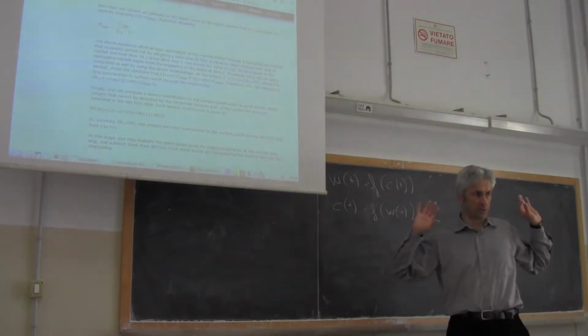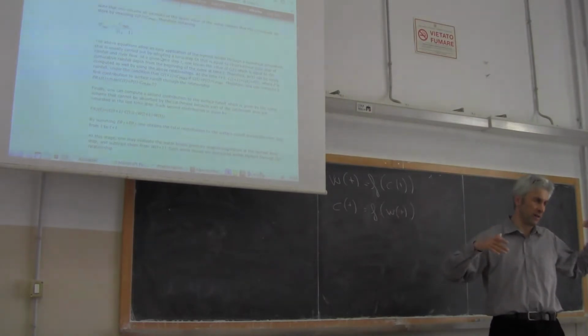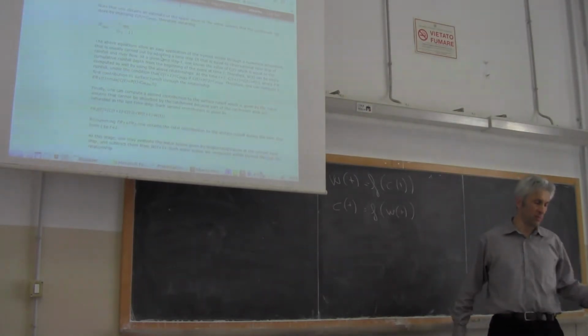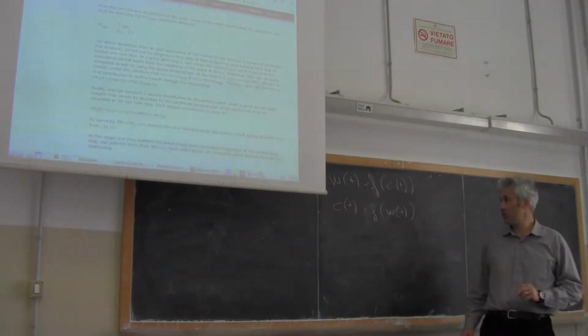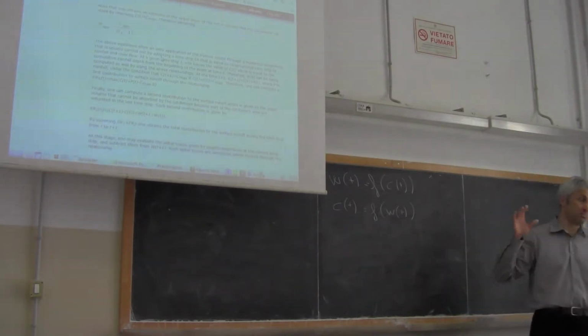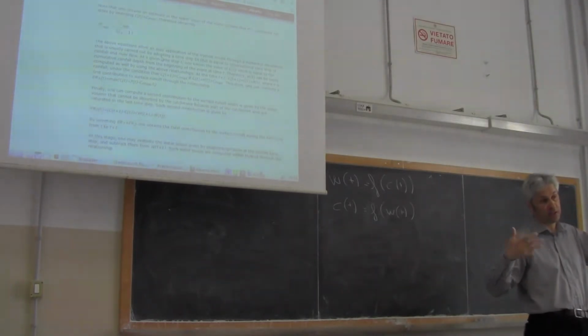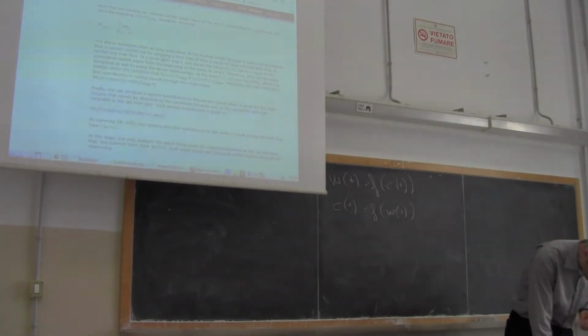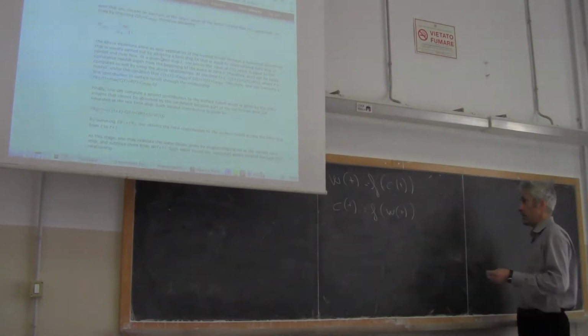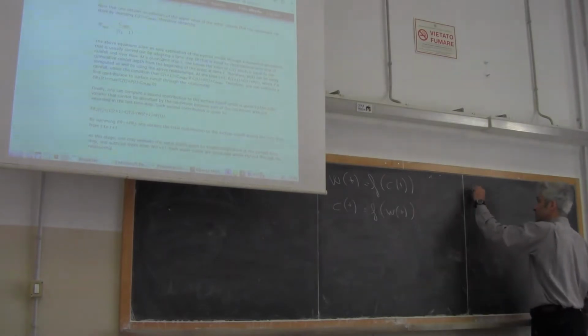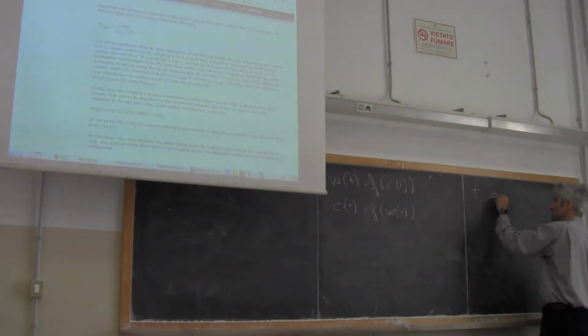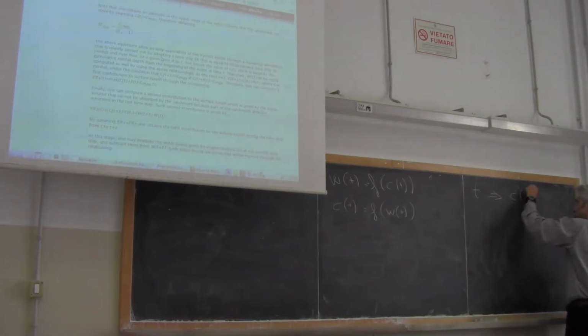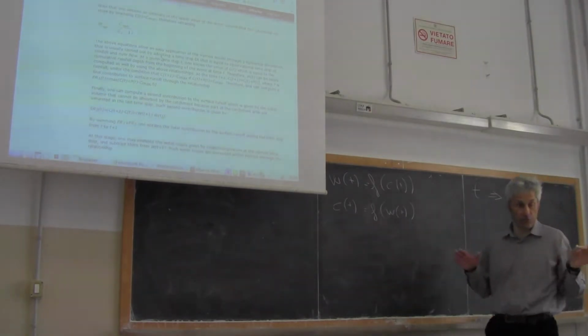We neglected evapotranspiration so far, so it's rainfall from the beginning of a given rainfall event. Let's say that it's rainfall from time zero. So at a given time step t, you know Ct, because you have observations of rainfall.